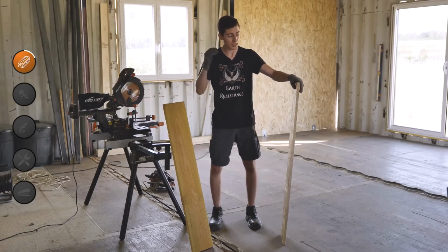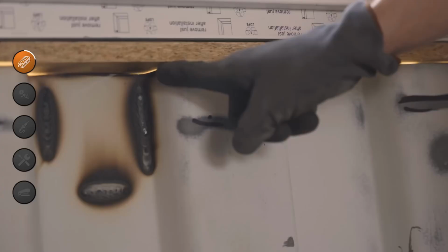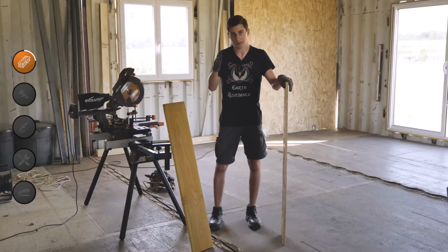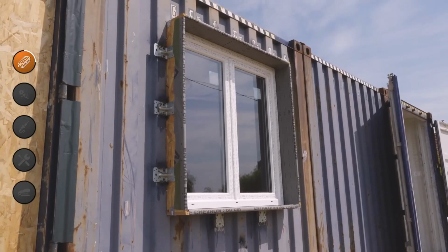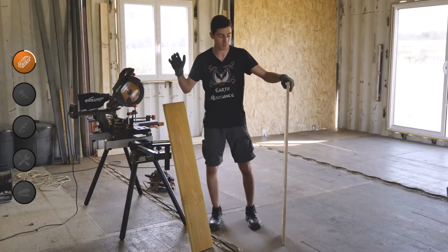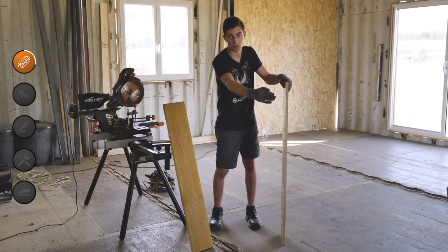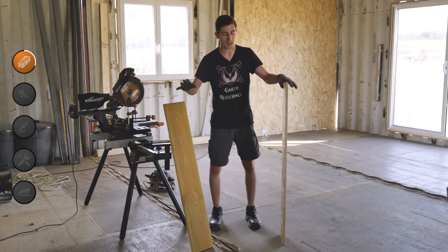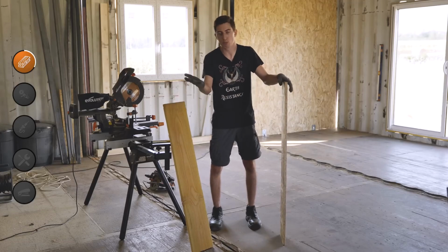When I come to place my oriented strand board tunnel on my container, it will rest on the inner corrugation. So it will be set 4 centimeters inside the house, and it will stick out 20 centimeters because I'll have 20 centimeters of insulation. So theoretically, I would need to make boards that are 24 centimeters deep, which I can do with formwork boards. Being off by 4 centimeters isn't a big deal, it still works. But oriented strand board is more flexible, it's easier to install.